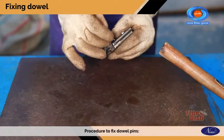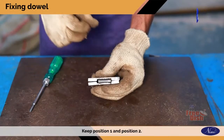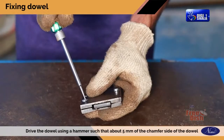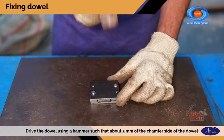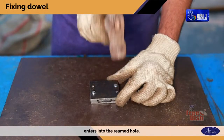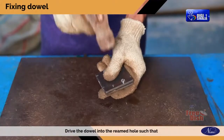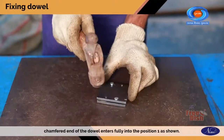Procedure to fix dowel pins. Keep position 1 and position 2. Tighten the socket head screw such that there is a gap of 1 pitch of the socket head screw. Drive the dowel using a hammer such that about 5 mm of the chamfer side of the dowel enters into the reamed hole. Check for the perpendicularity. Drive the dowel into the reamed hole such that the chamfered end of the dowel enters fully into position 1 as shown.